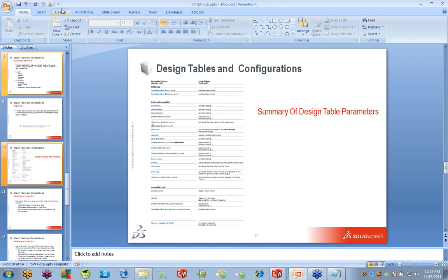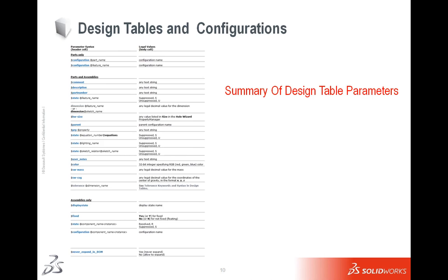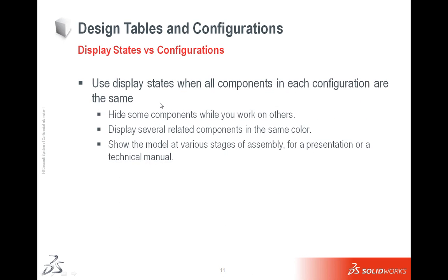Now the last thing I wanted to, well, actually there's a few more things in here. Let's see here. Just a general comment about display states versus configurations. How do you know when to use display states versus using a configuration? They're often confused. Well, display states should be used when all the components in each configuration are the same.